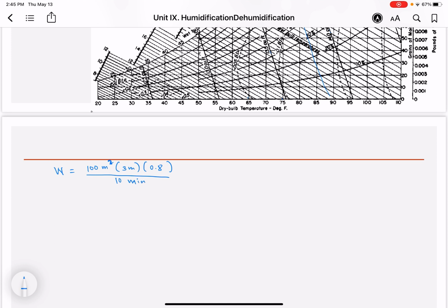So if I'm to multiply that, 1 over 13.7, the humid volume, that's cubic feet, times, so this is in meters, I need to, so this is per pound dry air. 1 meter is 3.28 feet cube, times, there are 2.2 pound per kilogram.